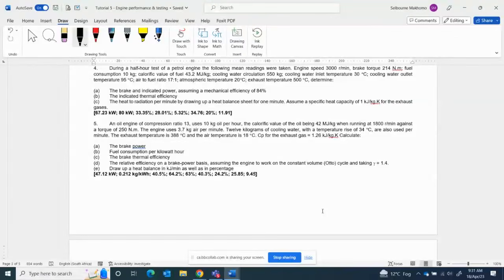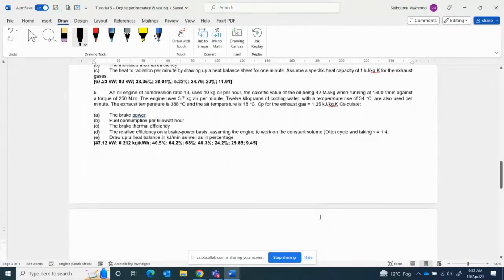Diesel. That compression ratio tells me that it's a diesel engine. But you see, 12 and 13 can be the borderline for a petrol engine and a diesel engine. So 13 can be either diesel or petrol. If somebody says 13 is a petrol, I would say, yes, it's petrol, but it's got a very high compression ratio. If it's diesel, yes, I'll agree with it. So a compression ratio of 12 and 13 is a borderline. So for now, we assume it is diesel.